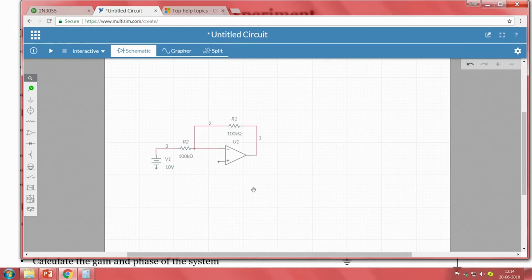Since the sensitivity factor of the input is 0.1 volt per degree centigrade, for 100 degree it will be 10 volt. If it is 200 degree it will be 20 volt, but the only thing is that your op amp operating voltage should support that, right. So, we have to use a combination of RF and R1 resistors at the positive terminal, so that the effect due to bias currents can be completely eliminated.